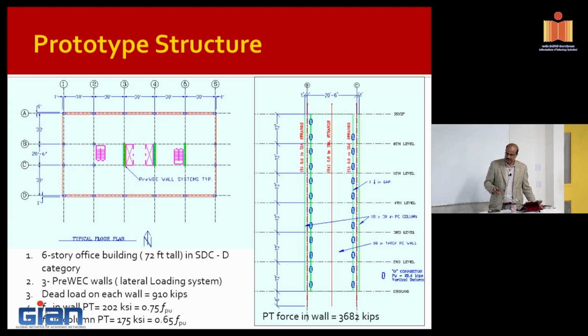Now, you calculate the total seismic force, and then half of that goes to this frame, half goes to this frame, and then you take this frame. So in terms of quantifying the moment demand, shear, everything is the same as what you do for cast-in-place. But when you design the connections, you choose the jointed connection with the hybrid concept, where you will have post-tensioning in the middle, and then rebar for energy dissipation.